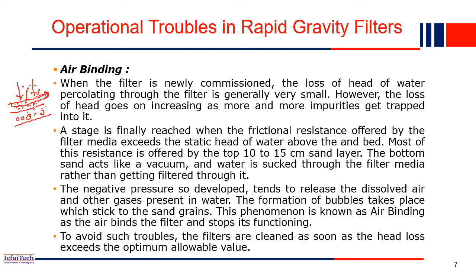the pores are still open, right? So this will create a vacuum here, because here the pores are open, whereas the top layer is completely packed. That phenomenon will create a negative pressure. Negative pressure means pressure will be high at the top, whereas the bottom pressure is less, right? Because of this negative pressure, the air and gas bubbles present in the water will simply go up, and this process we actually call air binding.